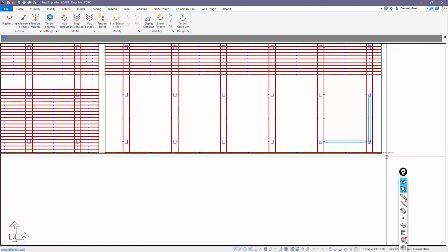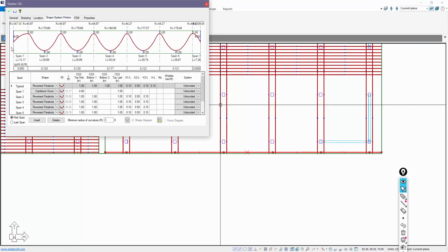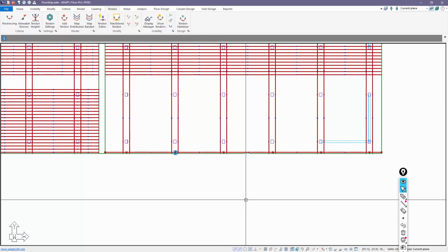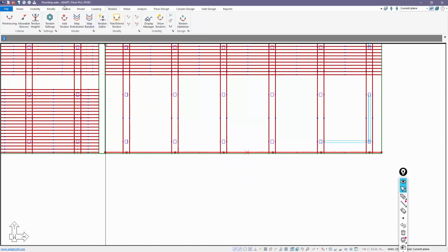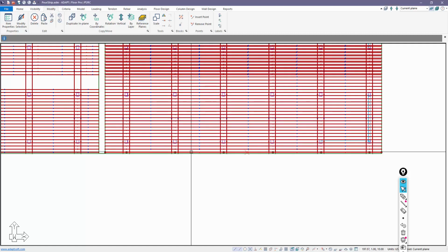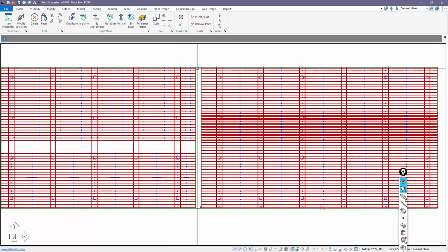Once we've done that, we can define the properties of this tendon: the number of strands, the effective stress or calculated stress or force, and the shape. Then we could again just copy that vertically using the modify option. So we'll do 1.87. This is probably 35. We have overlap, we have multiple tendons here, but that's basically how we would model against the pour strip. The same process could be done in the banded direction. These are just more modeled tendons.